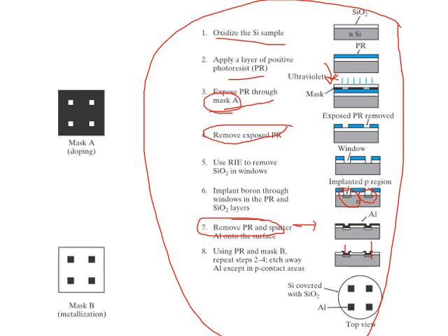So this is how the top view of the chip looks, or you can think, here the metallization is done only on these regions where it is shaded black. Other things don't require the metallization, so here only the terminals can be taken out, like source, drain, gate, and substrate. Followed? Okay, so here we'll stop, and we'll continue in the next class.